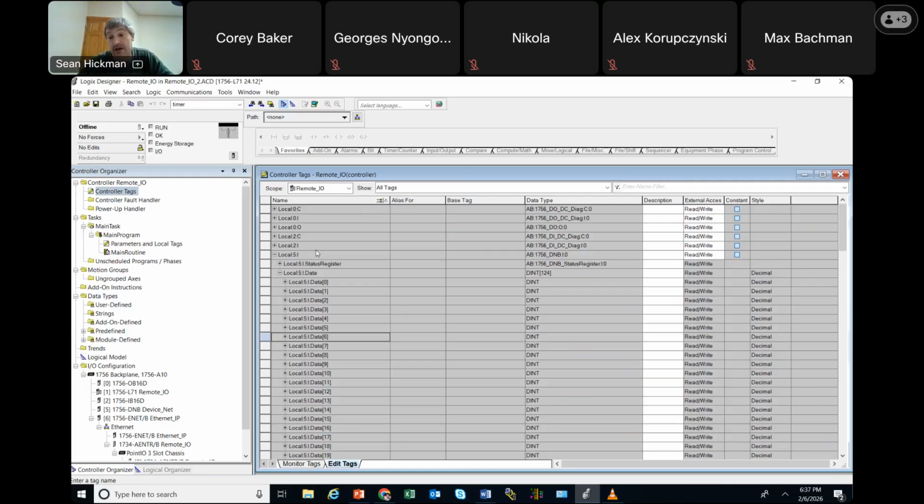If you're using a template where you went online and you discovered modules, disabled the keying, had everything just working great, then boom, you're in business right away to start programming. Well, why don't you do this, everybody? On that generic one on your main program here, why don't you make a subroutine called input mapping, and go ahead and map all your inputs. And if you want an output map, go ahead and map all your outputs.